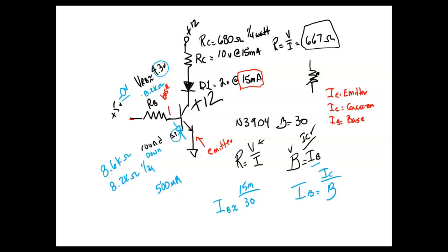When I worked in an electronic shop out of U.S. Steel, we had a transmitter. They had radio control cranes. I might have told y'all this before. That sucker had a fuse in it whose current rating was so small that if you checked it with an ohm meter, it would blow. So how did we tell it was blown? Well, we measured the voltage drop across it. If it was dropping whatever the batteries were, we knew it was blown, right? If it was dropping close to 0, we knew it was good.